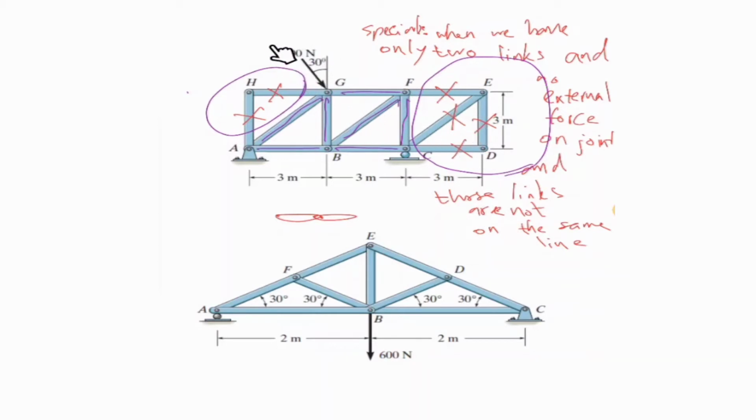For example, in one scenario you may have some forces here, another scenario you may have other forces here. And you may have this question, why do we need these guys? Because the scenarios are different. Sometimes you have a force here, sometimes you may have another force here, and you design it for all the scenarios which are possible for this structure. Then if you have just this scenario, actually you can get rid of these ones and you don't need to design your structure like this, but you may have some other scenarios as well.